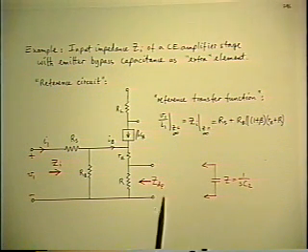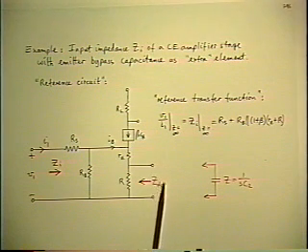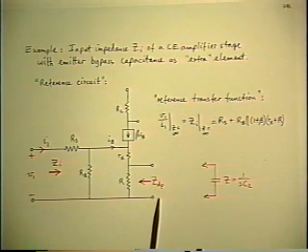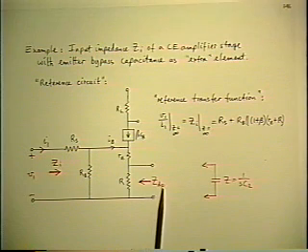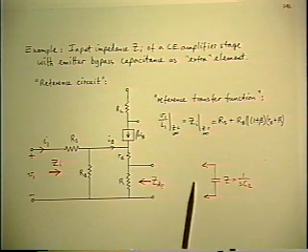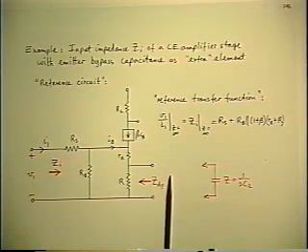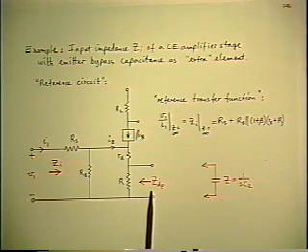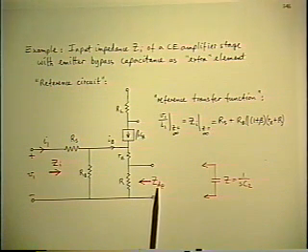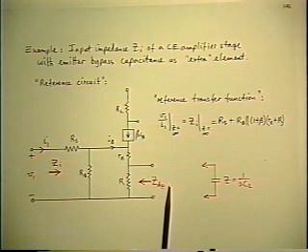The first one is we apply a second independent source across these two terminals, and I'm not going to bother drawing that this time either. I've done that enough times using Thevenin's, Norton's, or an unspecified source. Every time I've been saying it doesn't matter what the source is. So now I'm not even going to draw it at all. You just imagine that it's there. So there's a source driving into those two terminals. And the first driving point impedance is ZD, or RD in this case, because everything is resistive.